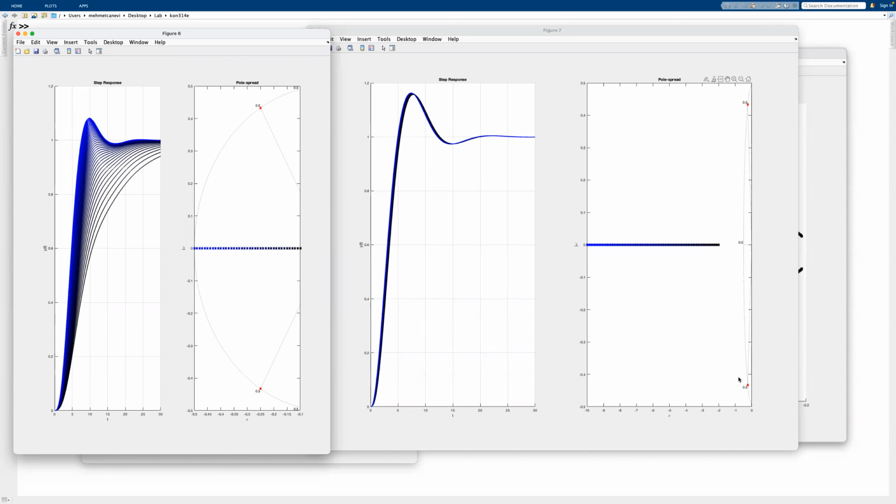These red ones are going to be the dominant poles that we call them, and the other ones are going to be pushed away. And we hope that the overall system behaves like a second order system, because we have tools for it. We have settling times, all sorts of stuff for second order systems, and we apply this to higher order systems with this dominant pole placement strategy.